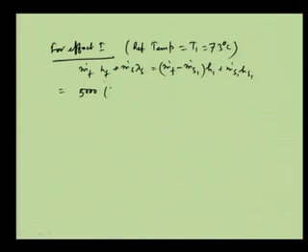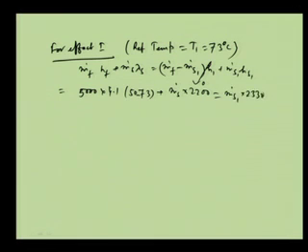And from there, if this is there, then we can write that this is equal to 5000 into the Cp of the feed, which is 4.1, into 50 minus 73. So, it is a negative quantity, plus m dot s into 2200 will be equal to H1, which is 0, this part is 0, and this part is m dot s1 into 2330. So, from this we can find out that m dot s1 will be equal to 0.944 m dot s minus 202.